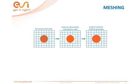The cell nodes near the geometry are then projected on it to capture the curvatures of the geometry. The image at the center represents a stair-step mesh. The image on the right represents a single-domain mesh. The surface mesh generated by means of projecting nodes represents a shrink-wrap mesh.